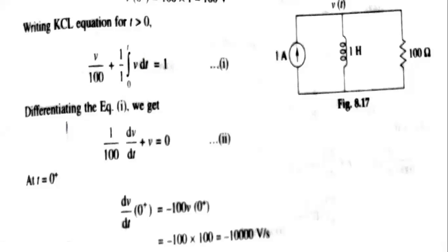But if you have L or C, you need to add that component, so that's why the additional components are mentioned. Otherwise, this is the I is equal to V by R case. We have the inductor here, maybe the capacitor or the RLC in other numericals, so depending upon the component placed in the circuit, you need to add. The important point is: for a parallel circuit, use KCL, I is equal to V by R; and if you are simplifying a series circuit, go for KVL, V minus IR is equal to 0. In this way, you can simplify easily.